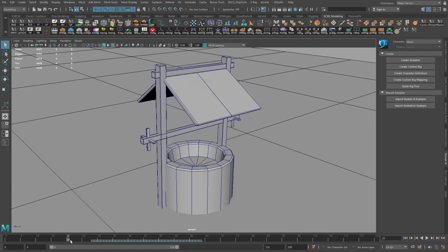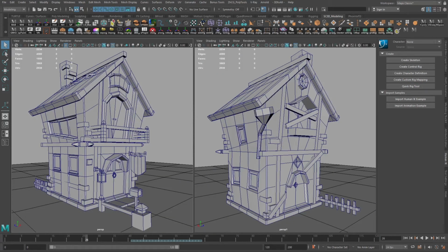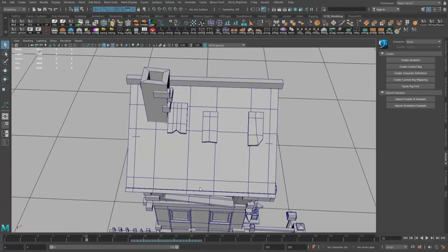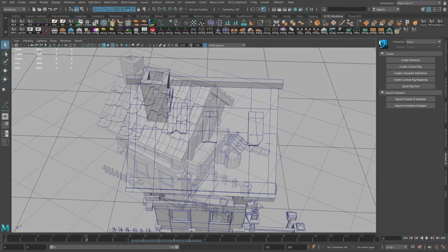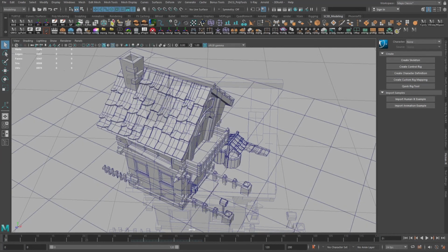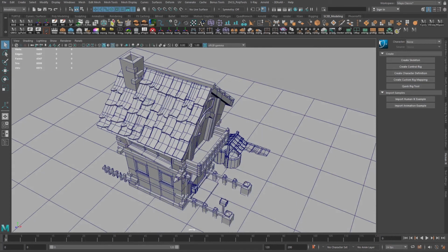I've duplicated the small roof from the abandoned house side and placed it here. On the roof, I've added a plank in order to get a clear view of the separation of the roof sides, same as on the house. Okay, so the last part of the house will be the roof tiles. I've decided to mention them at the end of the house modeling, as the roof tiles were created by instancing. Definitely you can create them one by one if you want to. However, my advice for such cases is to use instancing, as with instances you can easily tweak, reshape, or fix patterns.